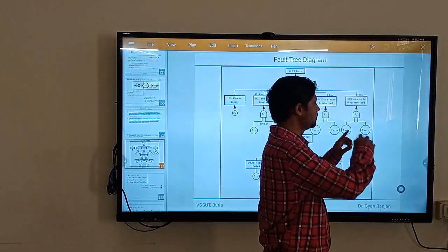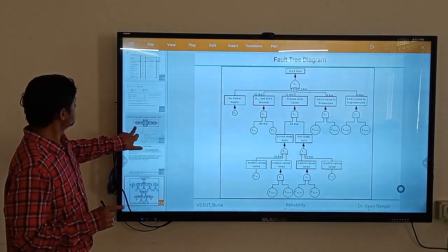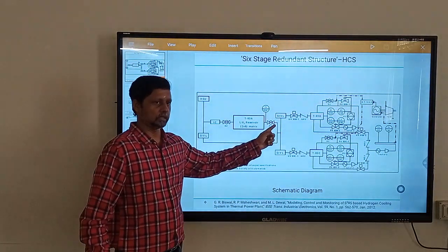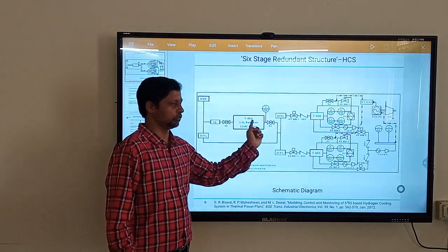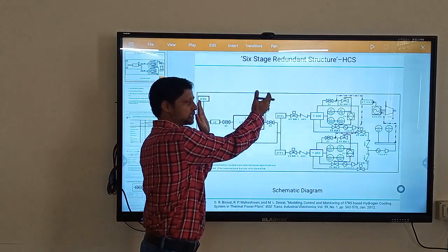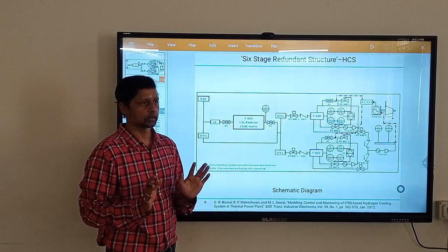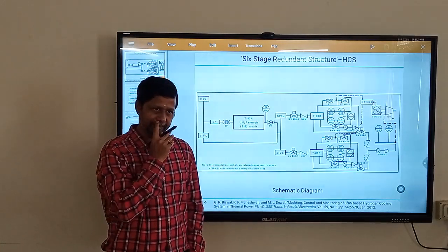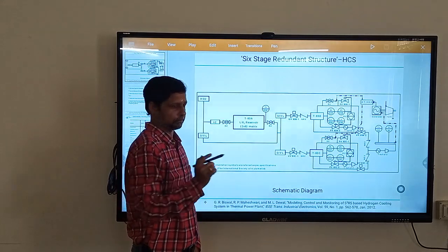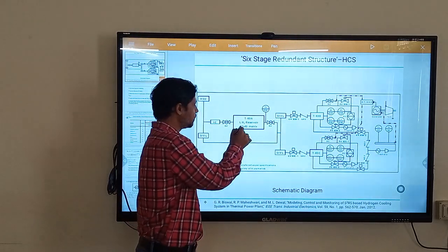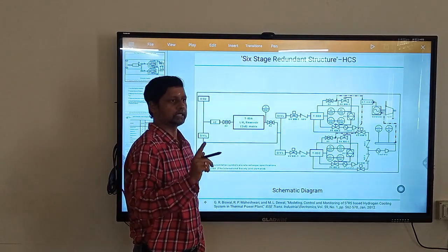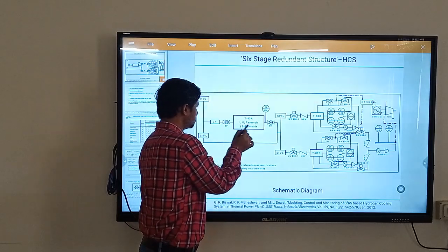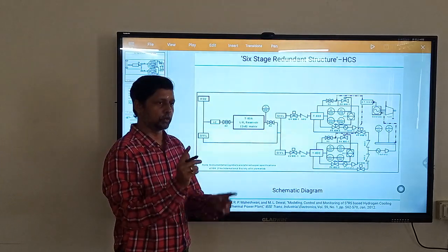So how will you represent it? The original design is this one, where the bypass line, in normal language, is in parallel to a reservoir. The question is, what if this entire stage chokes? When will it choke or block? If the outlet valve of this and this SIBL both fail at the same time. If only one of them fails, it will not have any impact, because the reservoir is itself a buffer. If one tank fails here, it is not an issue, and it will not suddenly impact my feeding process. Now, this stage fails and this stage fails, both at the same time.